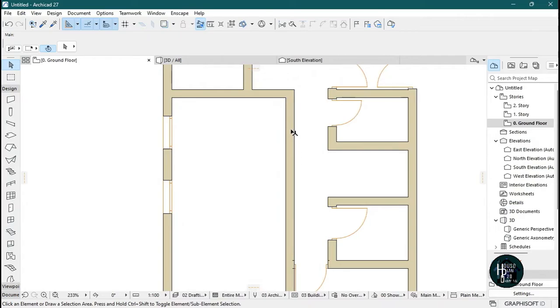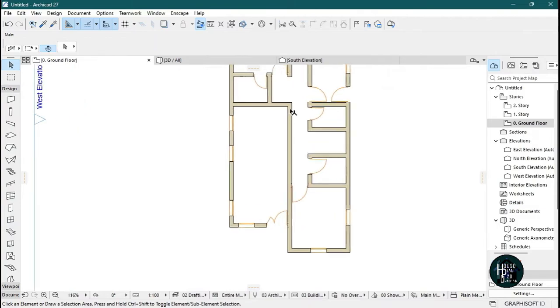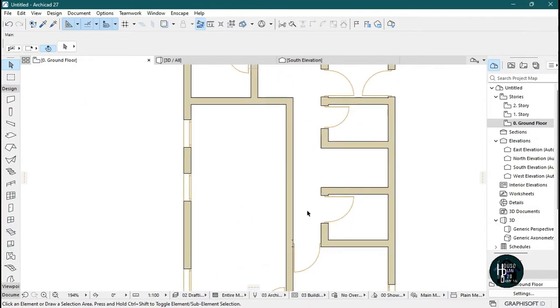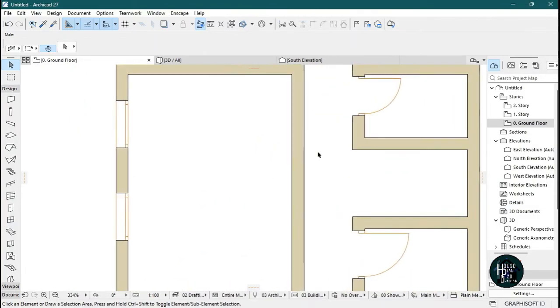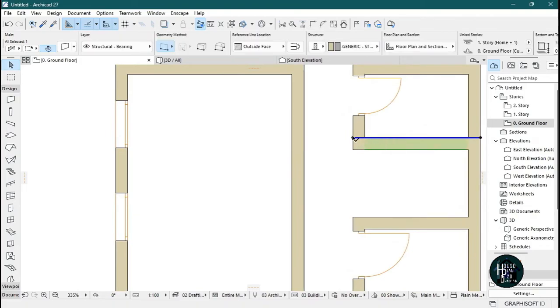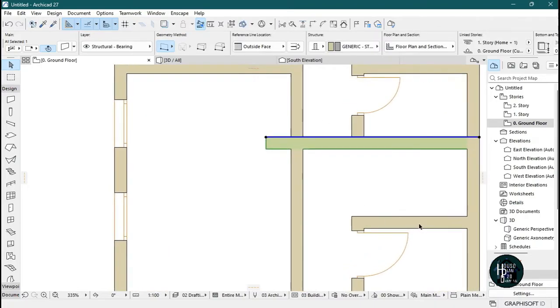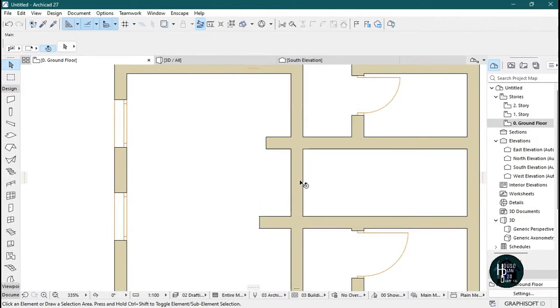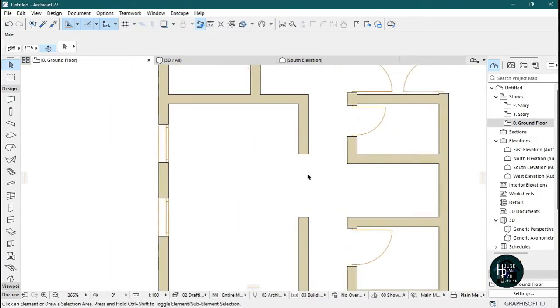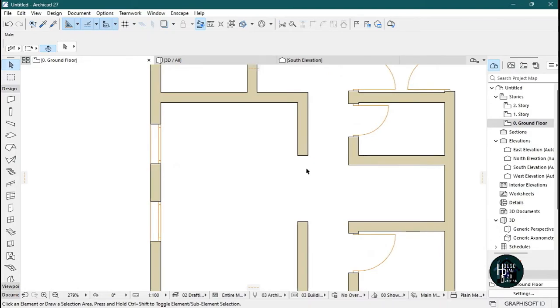Now I want to also open up this side here. As you can see, there's a straight line, but I want to also open up the wall. One easier way for us to do it is to click this, stretch it to this. Make sure you click on that node and stretch it to meet this side here. Click on the wall again, click this node and stretch it to meet this side again, then press Ctrl on your keyboard and cut out this part, this part, this part, this part, then cut out this part. That way we can have the sides being open.